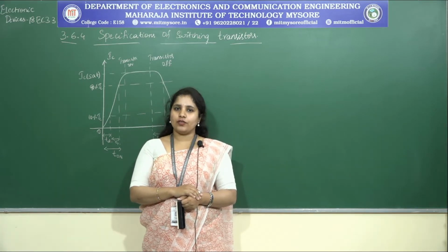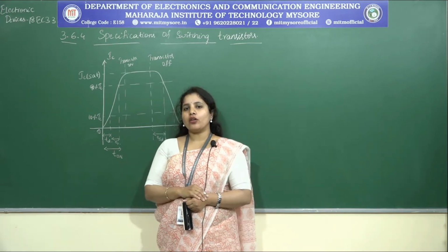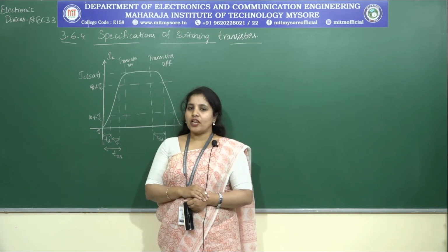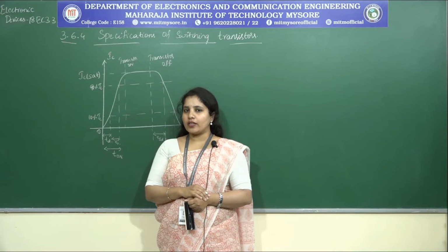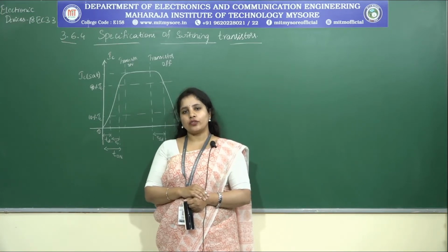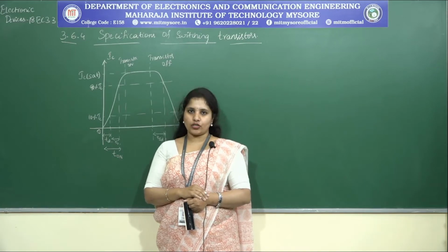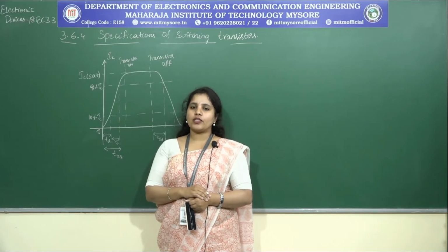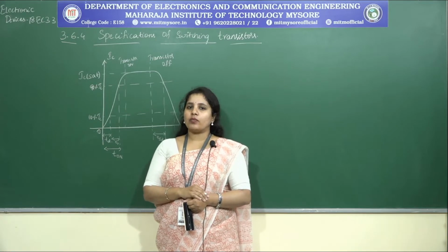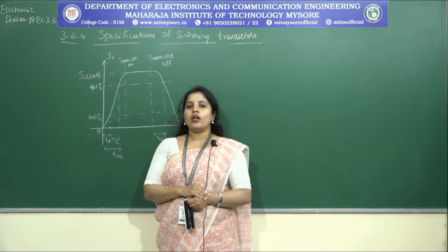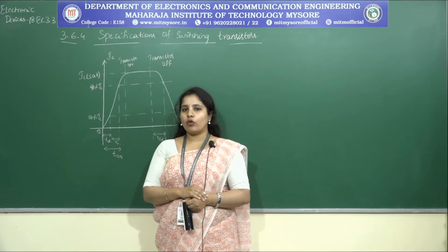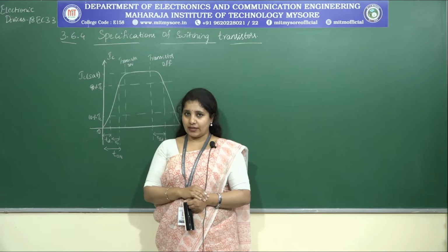In the previous session, we had discussed how switching basically happens in the cutoff region and in the saturation region. That is, if my transistor is in the on condition, that is in the saturation region, then it approximates the behavior of a switch in the on condition. If my transistor works in the cutoff region, then it approximates the behavior of a switch in the off condition, right? Now, under the same topic, we have one more topic that was left out, which is